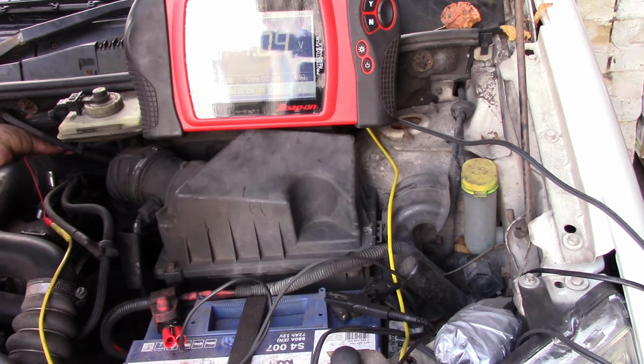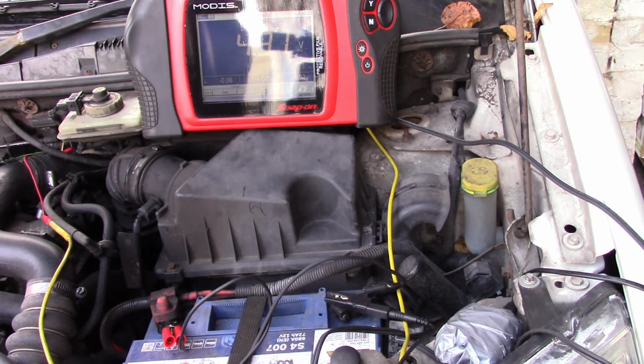Yeah, the probe was not properly in. Now as you can see, 4.91 volt. We have got that with the ignition on and engine off, and that's the 5-volt reference voltage from the ECU to the sensor. That also proves that we have a good ground as well, because as you can see, we can read the 4.91 volt.